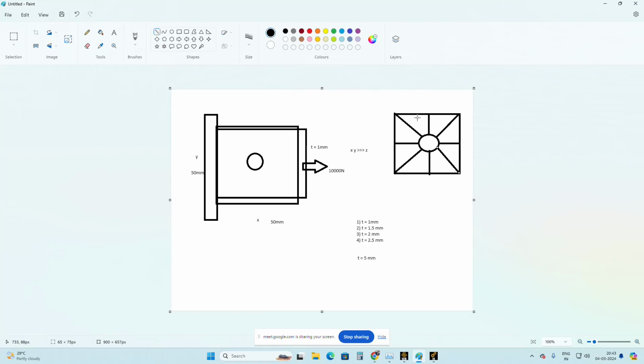You can see that each and every surface, this first surface itself, has one edge, two, three, four edges only. If you see all the surfaces, they all have a maximum of four edges. Initially, it had four outer edges and one inner circle edge, for a total of five edges. That is a parametrical surface. Now I converted those parametrical surfaces into biparametrical ones. So if I do this type of splitting over the structure and then do the meshing, I get a very neat quality mesh.